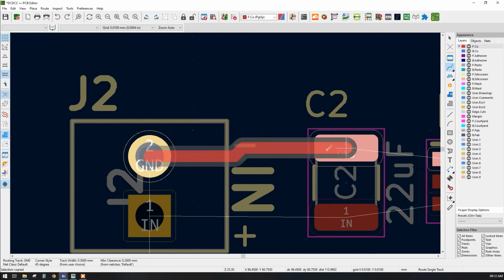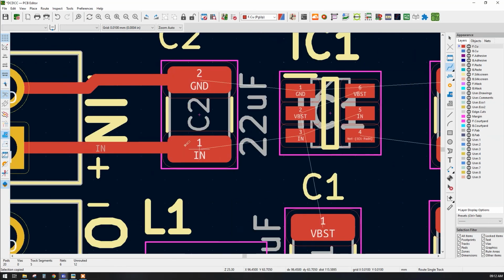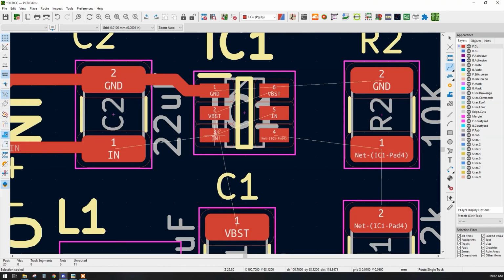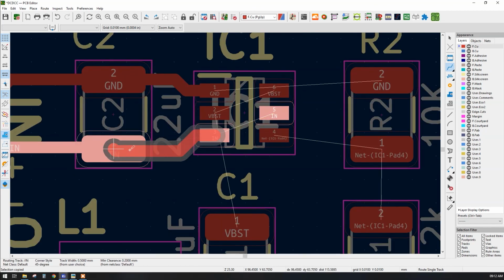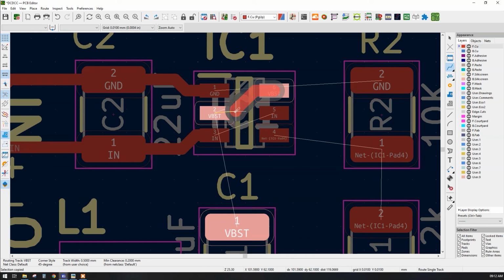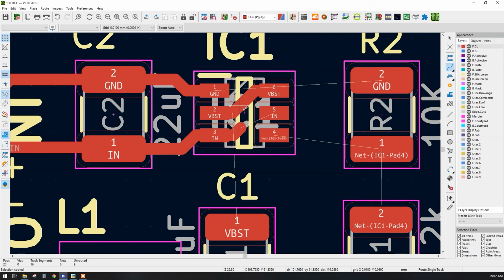Okay, so I will be using this 0.5 mm track to route. So simply click and click. Okay, so routing is a fairly simple process in KiCAD, and I will route for the single layer. For now, I will guide you on how to add the wires also.